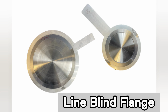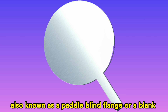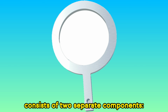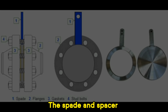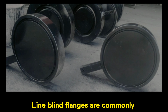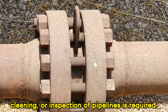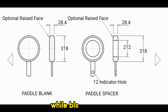Number 3. Line blind flange. A line blind flange, also known as a paddle blind flange or a blank and spacer assembly, consists of two separate components: a solid blind flange and a spacer. The spade and spacer are placed between two flanges and can be easily removed to open the pipeline or inserted to close it off. Line blind flanges are commonly used in applications where frequent maintenance, cleaning, or inspection of pipelines is required. The difference between blank and spacer is the incorporated bore: the spacer has it, while the blank does not.